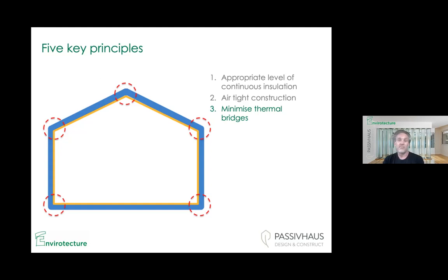And the other potentially worse aspect is that, due to the nature of a cold thing inside a warmish building, they can also be the source of condensation and mold. And again, windows are a good example, whether it's aluminium framed windows getting condensation on the aluminium itself, or just single pane glass windows. In winter, overnight in particular, they often get quite large amounts of condensation on the inside.